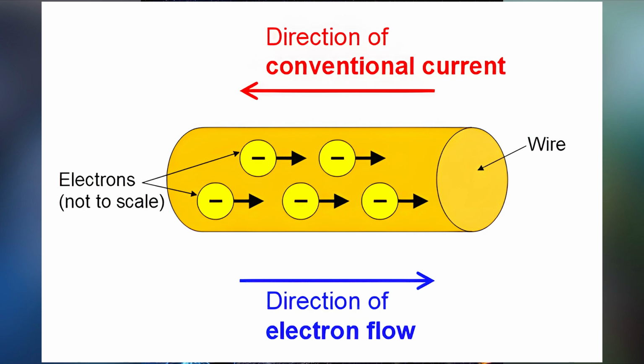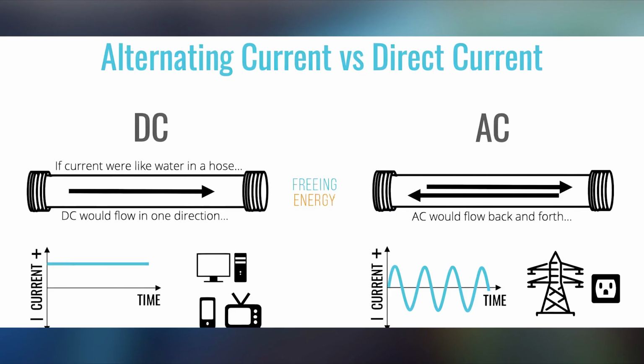There are two types of current that we normally talk about: direct current and alternating current. In direct current, there's a unidirectional flow of electric charge. That means the electrons start at one side, say the right, and they move over to the left, and they keep moving in that direction for as long as the charge is flowing. Now remember, they don't move in a straight line. They're always jiggling around, and there's some overall drift speed. But in direct current, the drift speed is always in the same direction. Direct current is provided by sources like batteries and solar cells, which are two common examples.